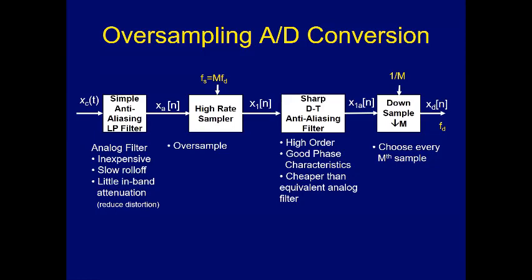There's one more little trick in our handbag that we can sometimes pull out. If I need to use oversampling a lot to prevent aliasing to the point where the sampling rate I end up with is way too high for the rest of my downstream processing system, we can do some of the job in the digital domain as well as the analog domain. And here's how that setup works.